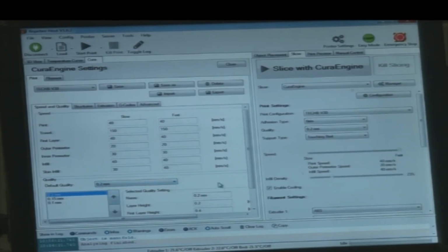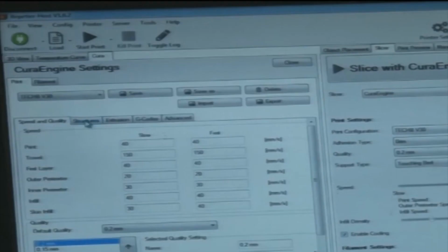Sometimes our dimension or profile shape is what is important. If the quality factor is not very important and only the profile shape matters, then we can go for rapid printing, that is 0.2 mm. Sometimes we feel that the size and dimension as well as quality need to be higher, so we can keep a 0.1 mm layer thickness.